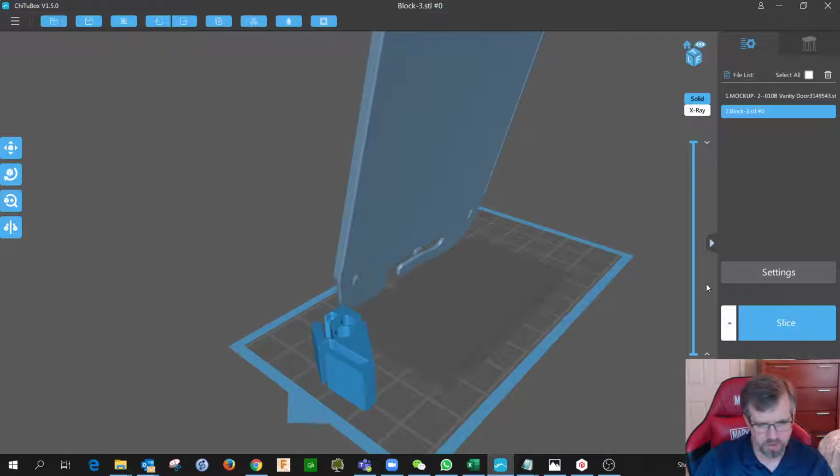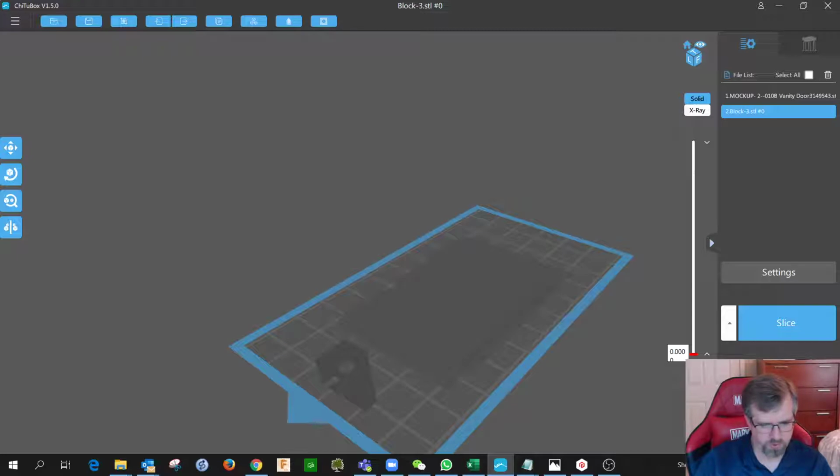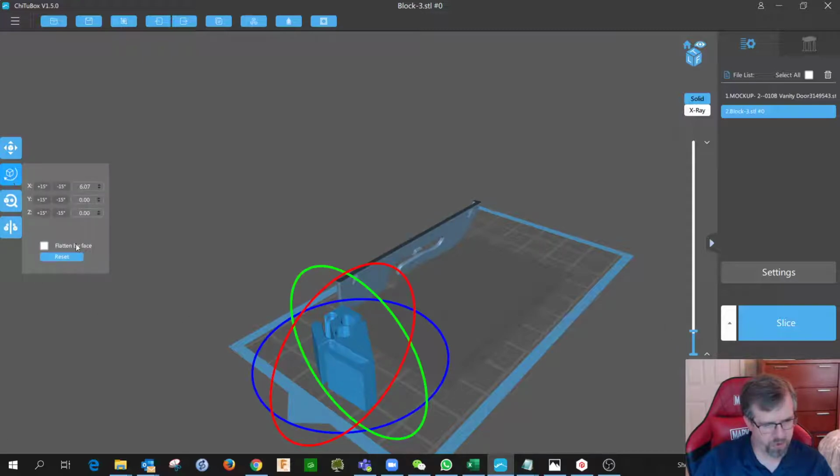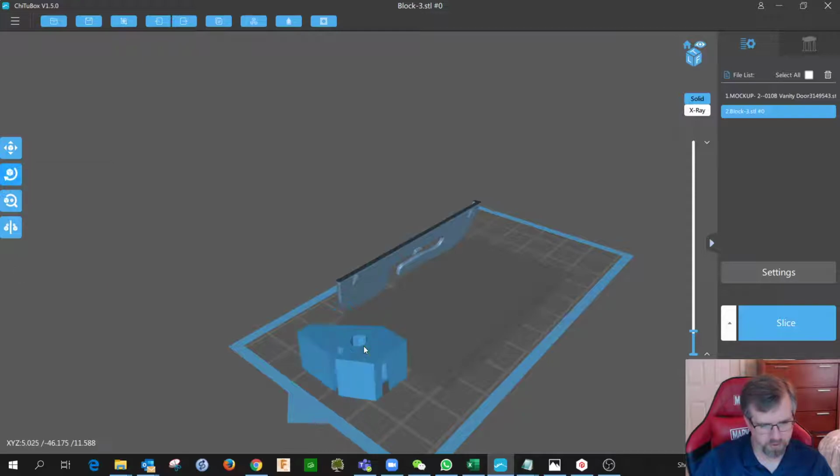And then if you want to get a sense of it printing, you can use this and slowly drag it up. What you're looking for is that there are no islands. Let's say there's an object that came off the side here and up, or something that started up here and connected higher to the side of it. I can show you a little better what I mean by rotating this to the wrong face for a second.